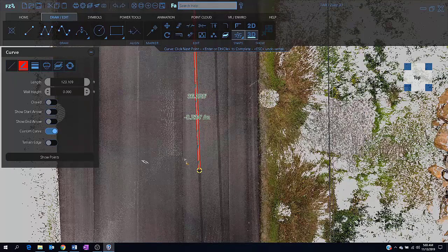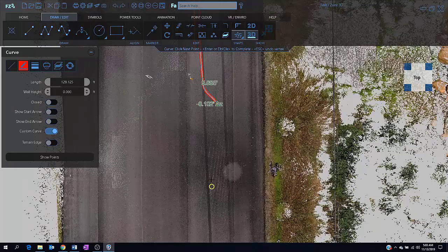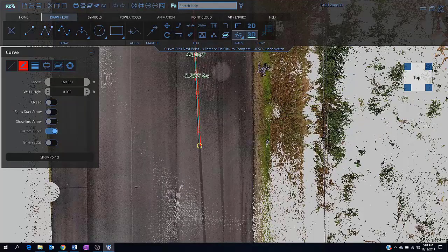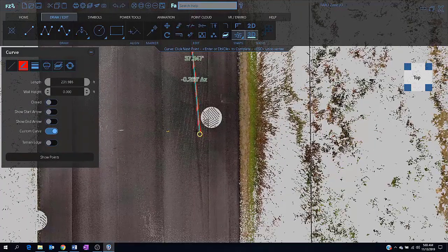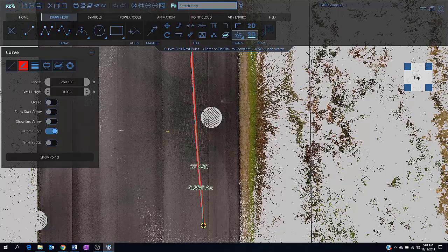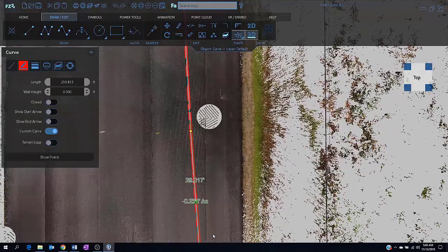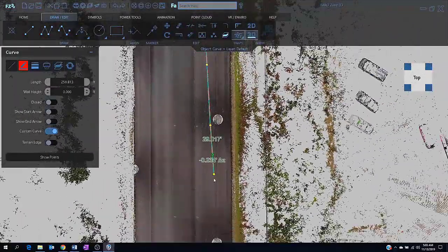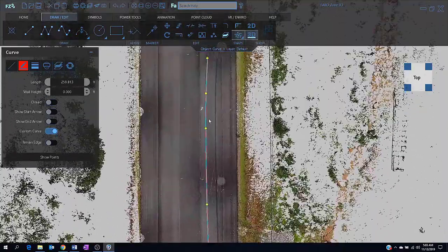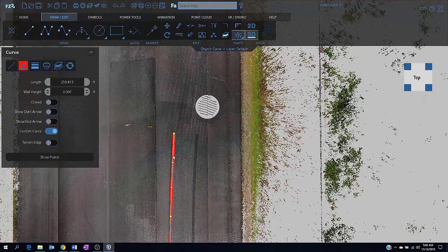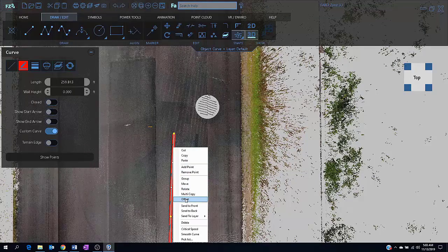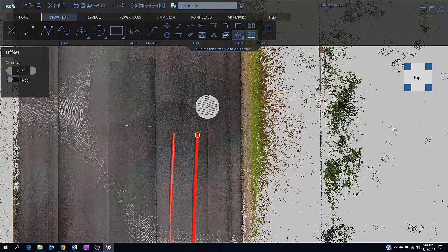We can just let this slide play through. I think the largest benefit from this is the production of the report, and you have the ability when the report is printed to add your name, your case number, your agency, location, case name, and in this case, it shows you the number of skids that were used to calculate your speed. One other thing I wanted to point out is there is a refresh button on the right side of that panel. Just be sure that when you're adding more than one skid, that you're refreshing the calculation so that it shows the combined speed from multiple skids instead of just the one speed. This is a report that's generated by the skid analysis tool.